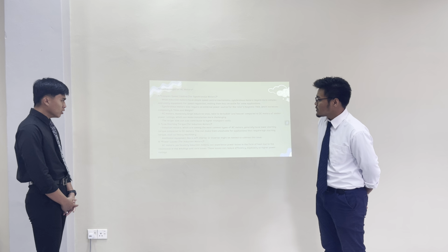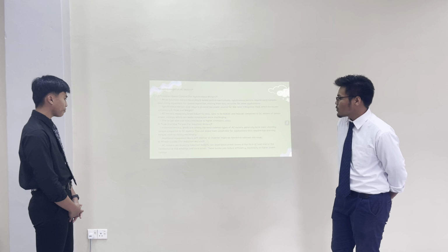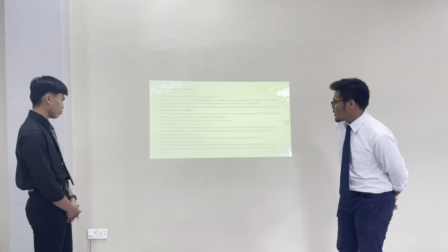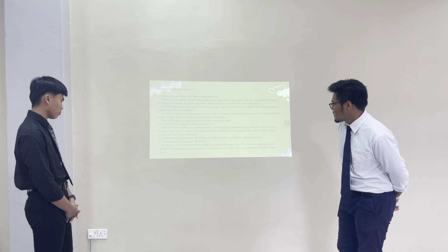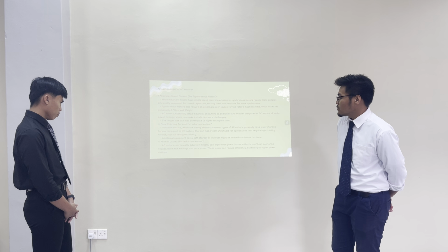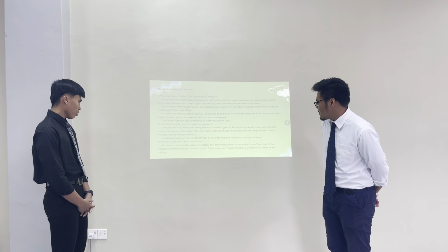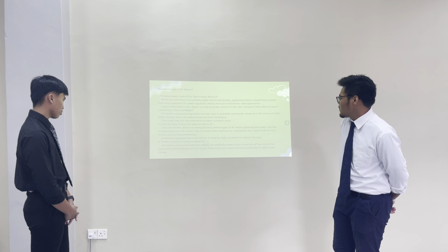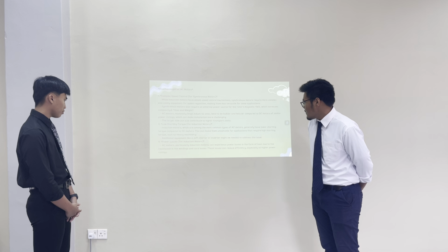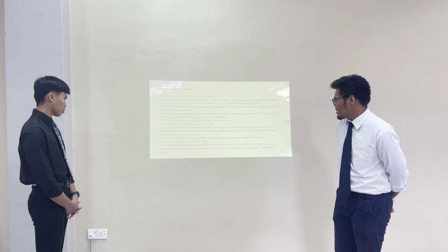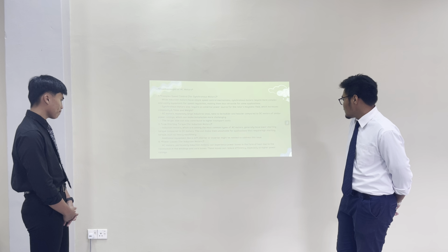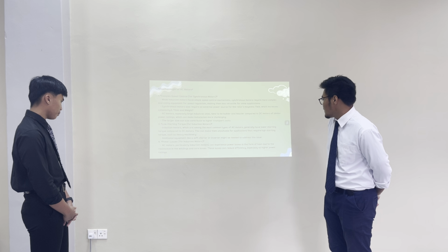Number 3, low starting torque for induction motors. Induction motors, which are among the most common types of AC motors, generally have lower starting torque compared to DC motors. This can make them unsuitable for applications that require high starting torque, such as heavy machinery. Additional equipment like a soft starter or inverter might be needed to address these issues.